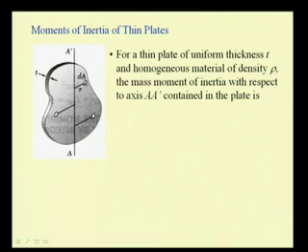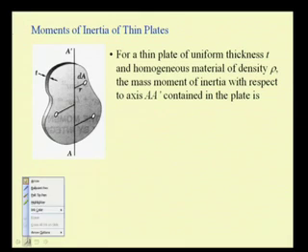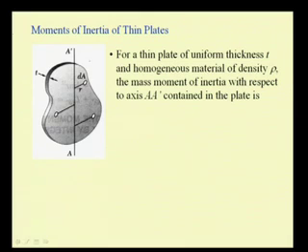The elemental mass is nothing but dA times T, the thickness, which gives the volume of that element, times the density of the element. So, rho T dA will be nothing but the corresponding mass element dm, equal to rho the density times the thickness times this differential area dA.